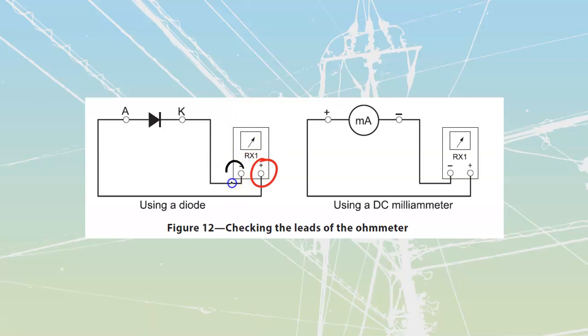Really, we just go off of which one of these is red and which one of these is black. Quite honestly, that is always going to determine which one of these is positive and negative. We do use the red and the black jacks on our meters for some stuff. The black jack, I want you to just think about wearing black shoes. That's where you're standing. The red is where you are always looking over. Think about red laser eyeballs. That's what our meters have, but it's actually where we're standing is where we're sending current out, through, etc. back down into it. So to test the SCR, first you have to know which is the positive and negative on your meter. All of this thing about verifying ohmmeter polarity, don't worry about it, because just use the red and the black off of it.